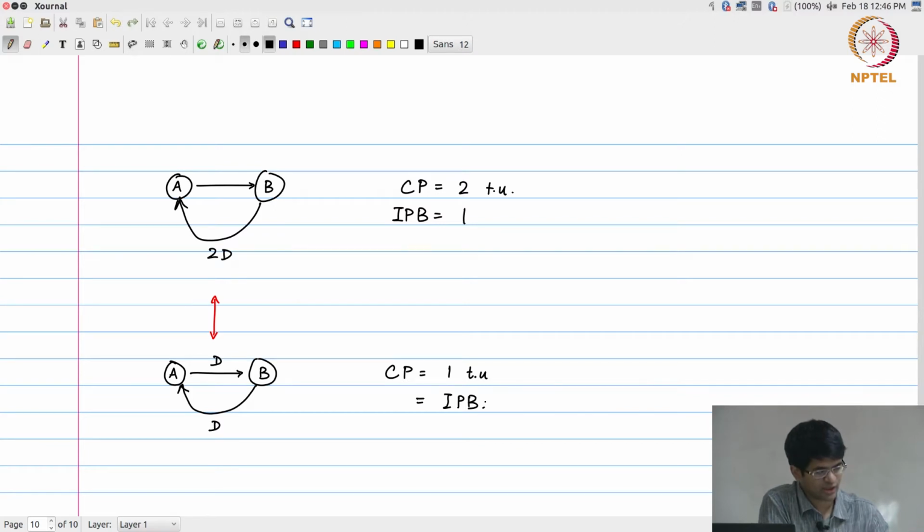If I look at this, what have I actually done over here? I have essentially taken this as my cut set. Is it a feed forward cut set? No, because one edge goes from A to B and the other edge goes from B to A, but I have still applied movement of registers across this cut set. Effectively, the way that you can look at it now is, I can choose any cut set, it need not be feed forward alone, it is just that in one direction if I am adding registers, in the other direction I should be able to subtract registers, right.